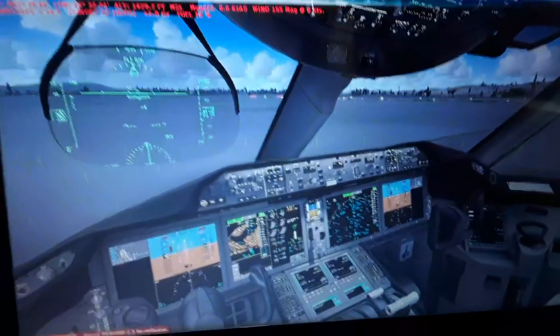Also, we have the artificial horizon with the attitude indicator, the pitch ladder in degrees, and the bank angle in degrees. We also have the LSZH localizer, the instrument landing system, which receives from the onboard antennas of the aircraft the radio frequencies transmitted from the runways we use for takeoff and landing. So we have a unique localizer for each runway, with a unique frequency and magnetic heading. We have to tune a separate localizer frequency for each airport.